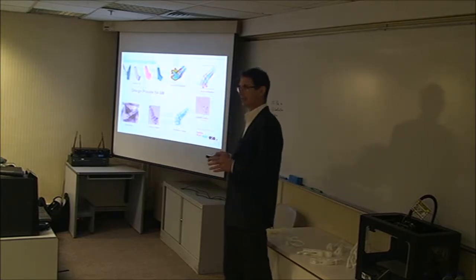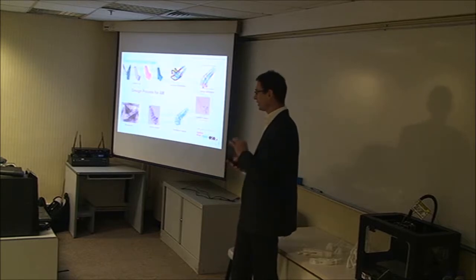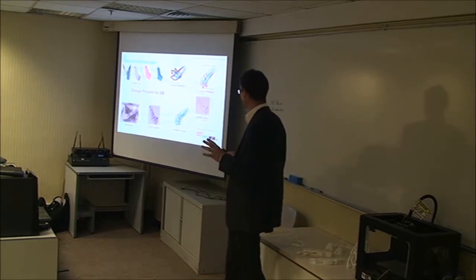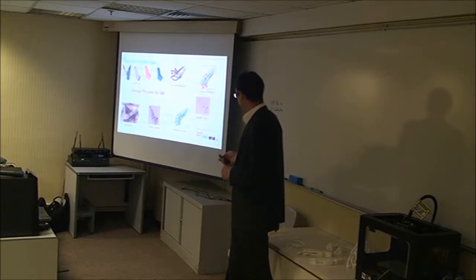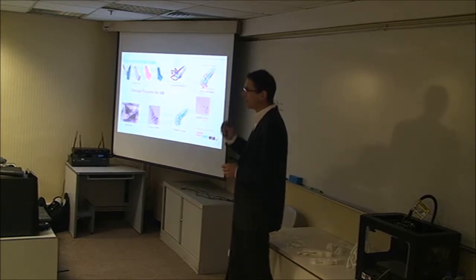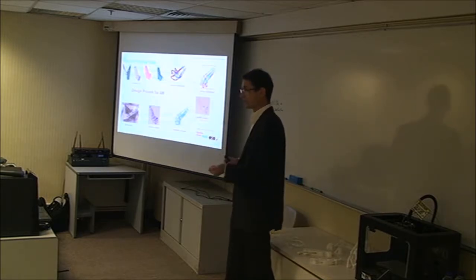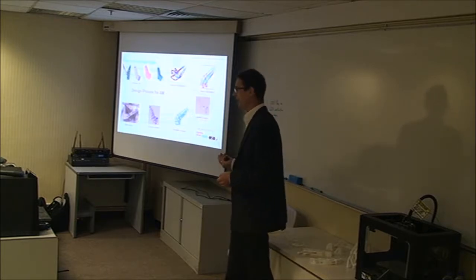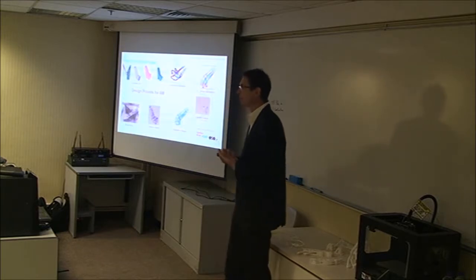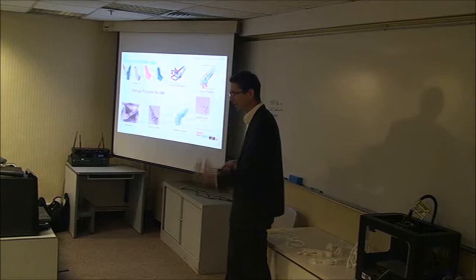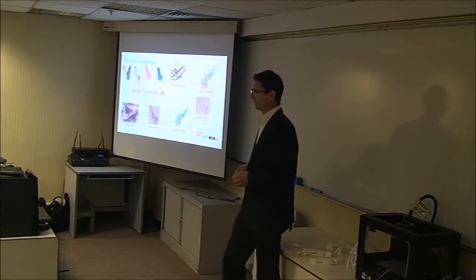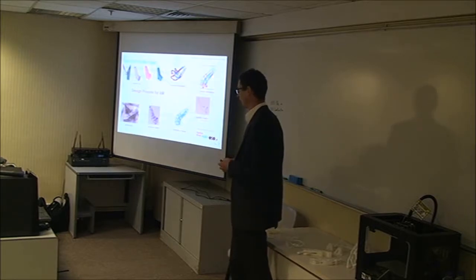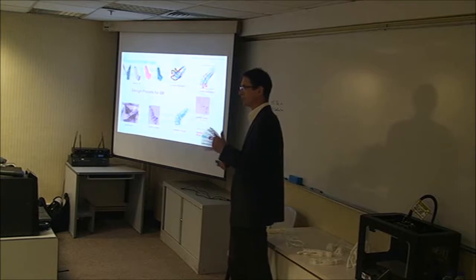As that part is not allowed to fail at all during the launch, it's only around 5 minutes that it will see loads in space. There is not a lot of vibration. So in order to be sure that it will withstand the loads, they actually printed 2 parts in one printing process. One part was tested, and when the test was good, then they used the other part to mount it to the satellite. Otherwise, they would not have been sure that the material properties are fine, that all the parameters of the printing process were defined in the right way, and so on. So quite some effort, but the number of parts they had to print is maybe 5.